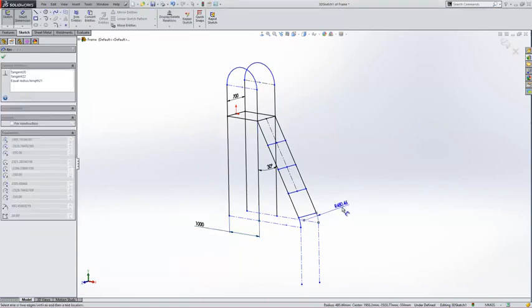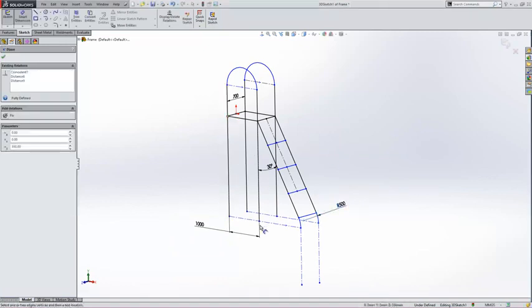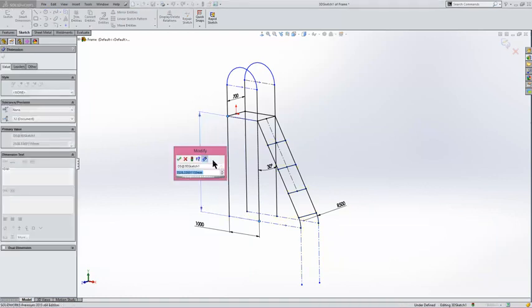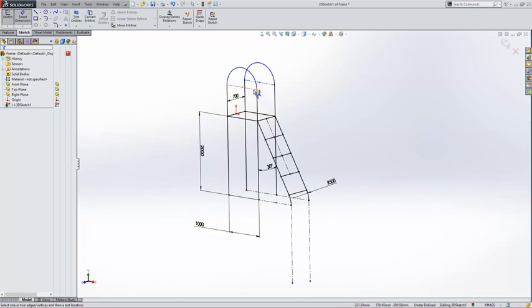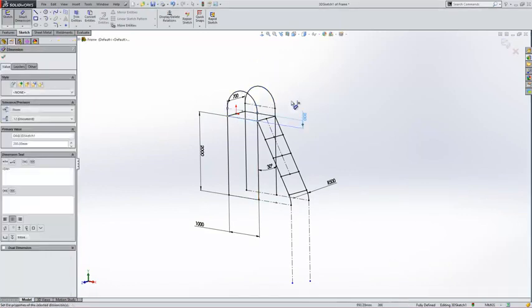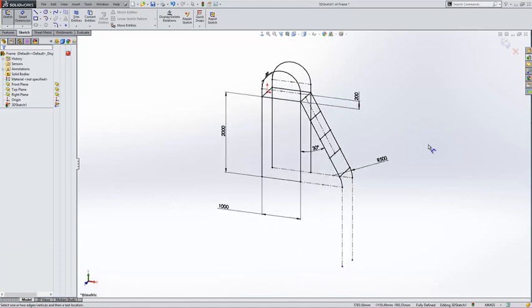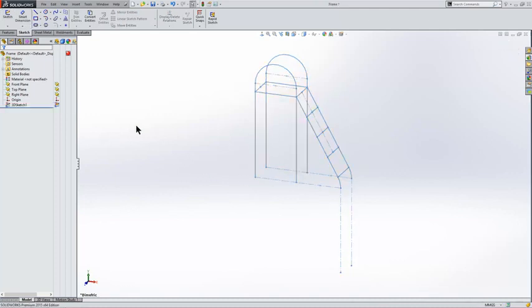We could put a radius of, say, 500. And then a height, same again, diagonal to diagonal, tab, tab. We can do a Y of 2000. And we'll have an overall height of this, say, at 200 mil. Alright, so our sketch is fully defined. I'm happy with that, our 3D sketch. So let's exit that and move into creating our 2D sketch.